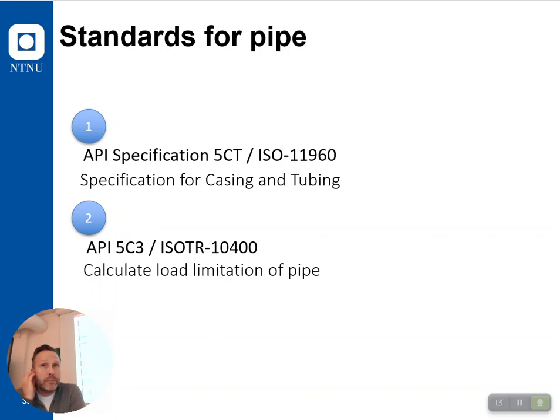Maybe they have lost thickness. But if the string that lost thickness still meets the requirement from the von Mises, it is always safe to use them, maybe from class 2 or class 1. Is it really safe to use these again? Absolutely. Yes, no problem.